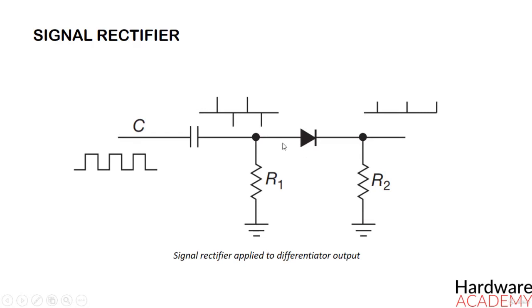And the reason is because if the input square wave is less than 0.6 volts peak to peak, this diode won't reach the conducting point, which is the forward diode drop, so it will block all the current trying to pass through it. If this is a problem, there are various tricks to circumvent this limitation. One possibility is to use hot carrier diodes like Schottky diodes with a forward drop of about 0.25 volts. Before showing you another possible solution, I want to explain why the signal looks like this here.